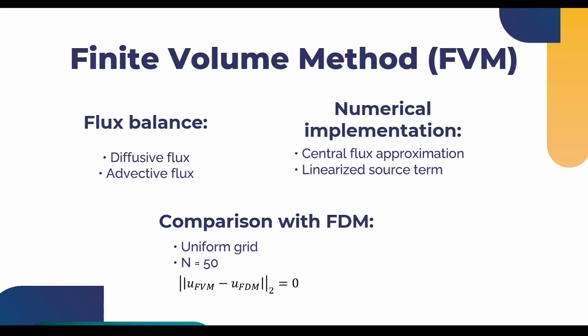We also solved the problem using the finite volume method. Instead of focusing on points, finite volume methods balance fluxes across control volumes. We use a vertex-centered approach and approximate the fluxes at the cell interfaces using central differencing. This ensures that mass is conserved locally within each volume.